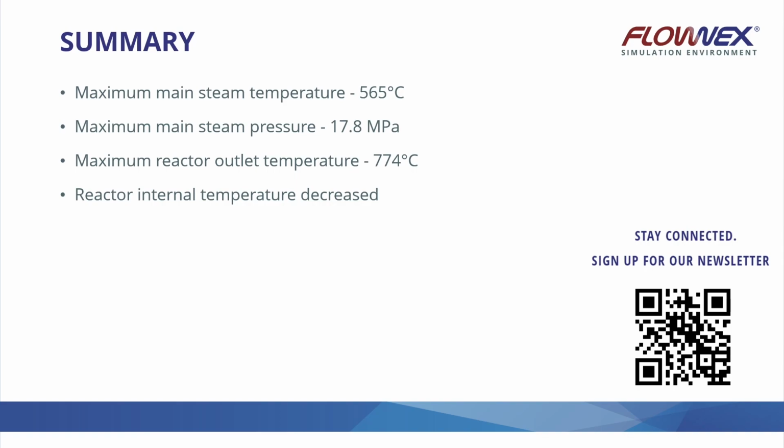We also looked at the conditions within the reactor and saw that the negative control rod reactivity was the main drive in total negative reactivity in the reactor. This led to a loss in fission power with only decay heat left over. We saw that running the circulator at low speed was sufficient in removing the decay heat and that the temperatures safely decreased over time.